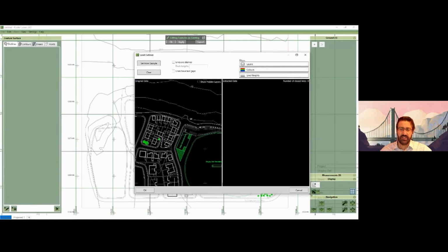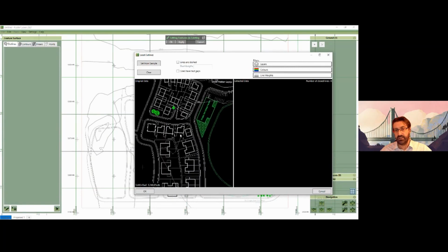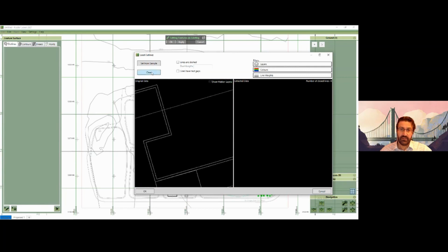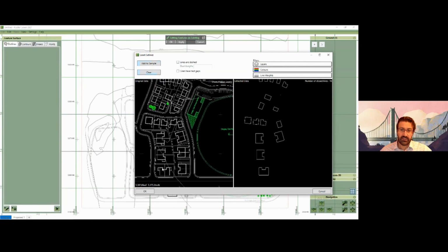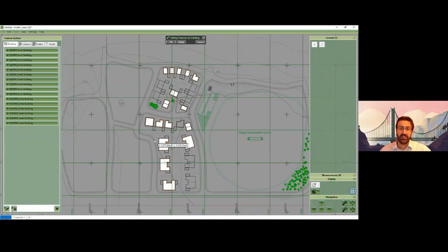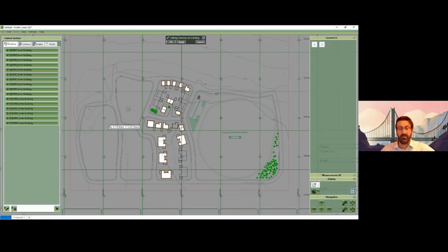So potentially all of these entities could be used, like the road outlines could be used to define a road. Let's see, so I'll clear the sample set from inner line. Okay, and that's grabbed a good percentage of the building pads to save me having to trace. In this example, it's not a huge time saver, but quite often we get projects with, say, 50 plots, so that would be a good time saver if you could extract those directly from the PDF.